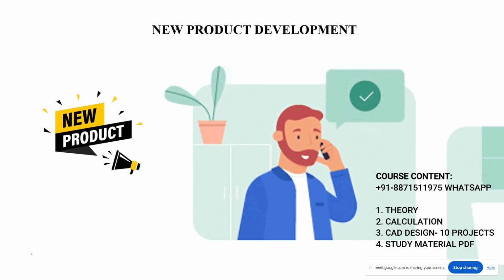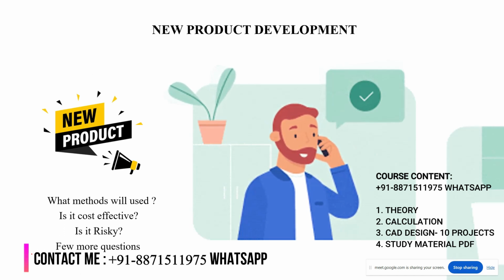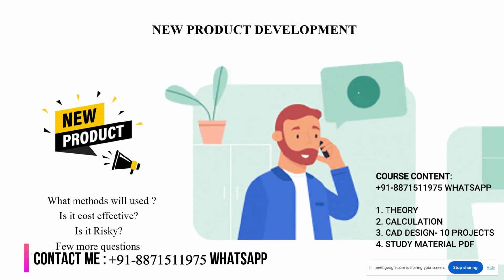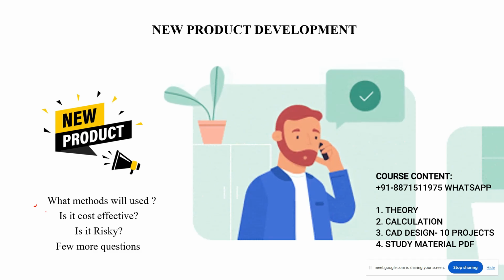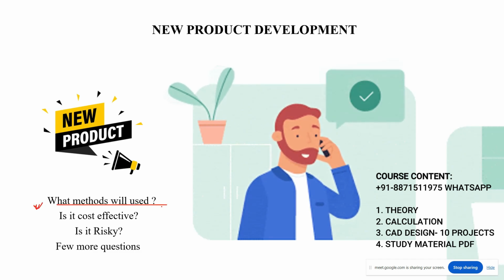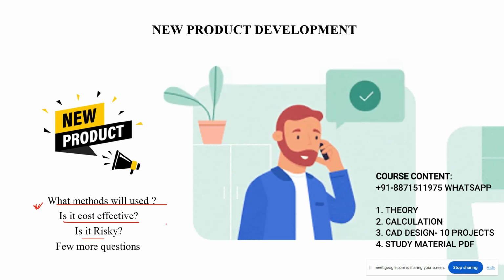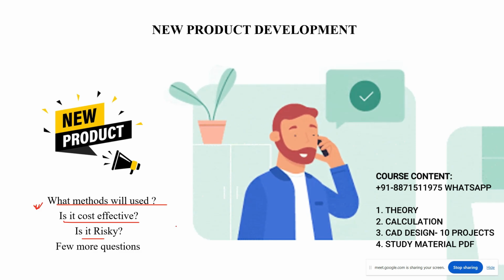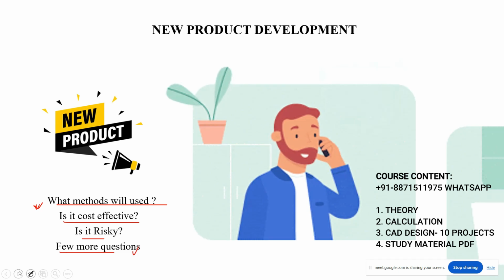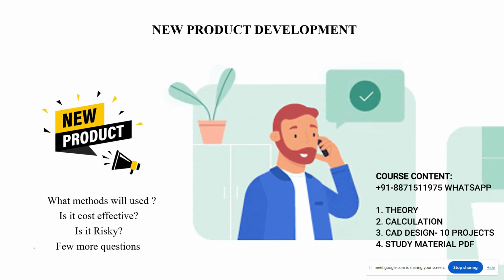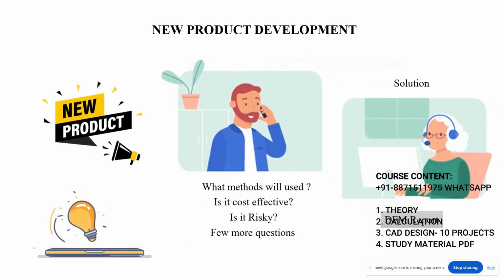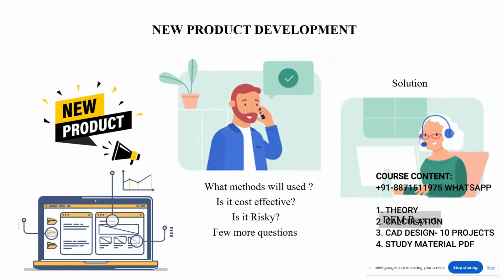For example, if we are dealing with new product design and development, where the company or the customer is designing a new product, these are the questions which will arise during the designing. What method will we use for molding, and is it cost effective or not? Is it risky? For example, if we are using a slider or lifter mechanism, it can break during production, right? And a few more questions like that. So DFM provides the answers to this type of questions, so DFM is a solution for them, right?